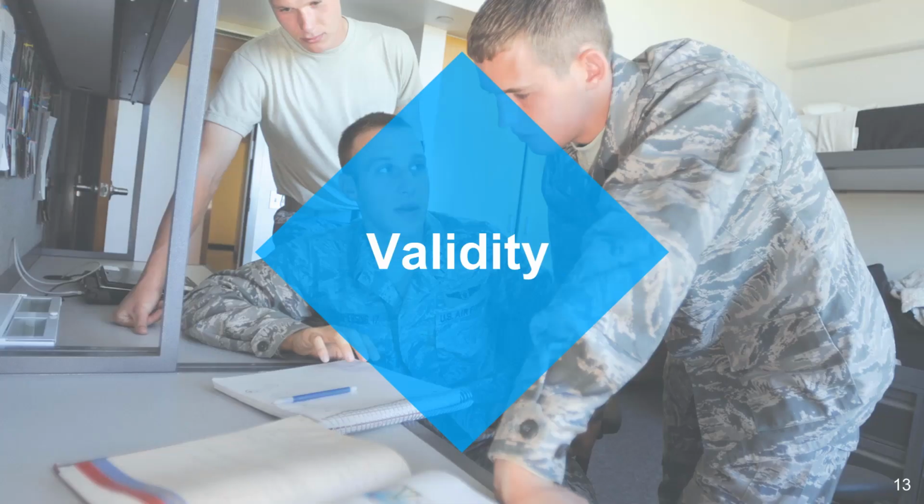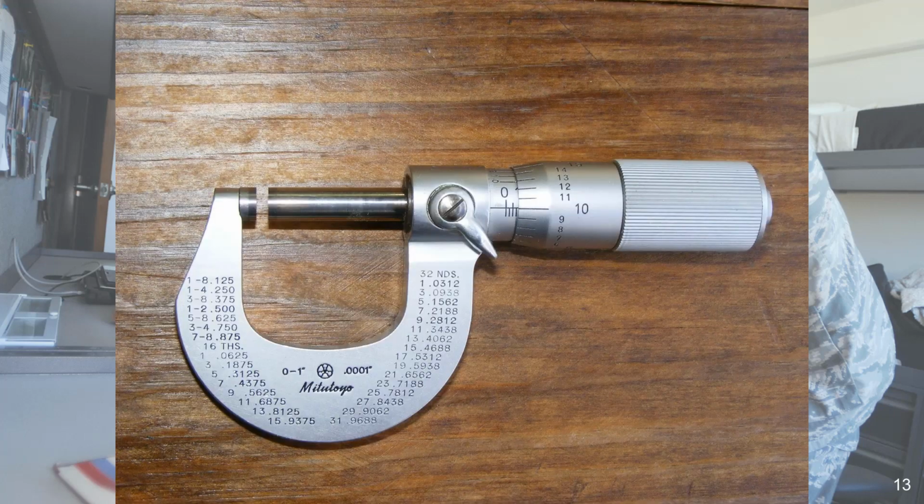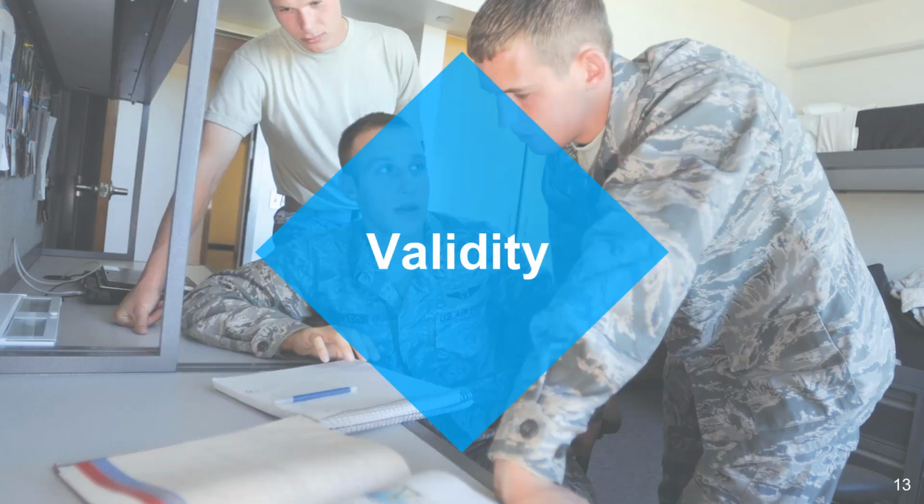A measuring instrument is valid when it measures exactly what it was designed to measure. For example, mechanics who use a micrometer to measure the diameter of a bearing must be sure that the contacting surfaces of the bearing and the micrometer are free from grease and dirt. Otherwise, they will measure the coating in addition to the diameter of the bearing, and the measurement will be invalid.